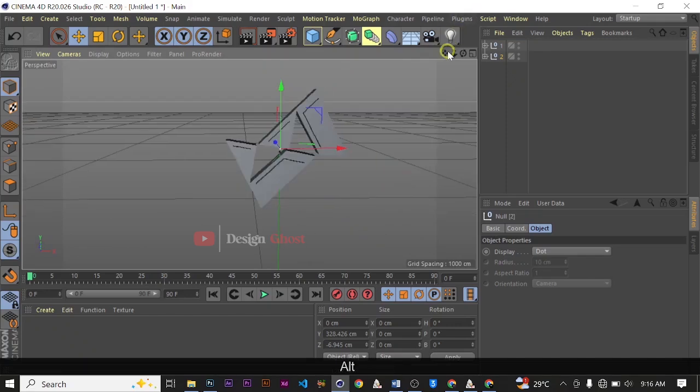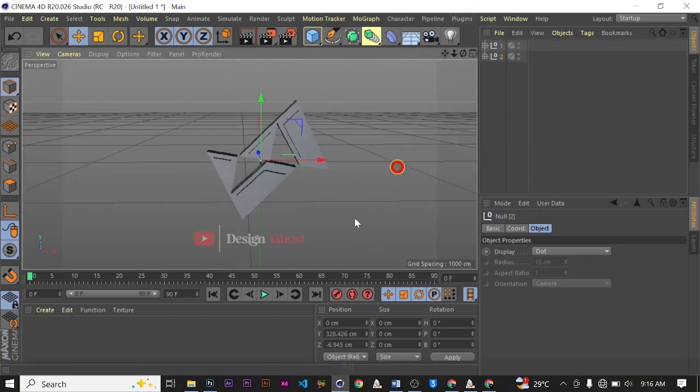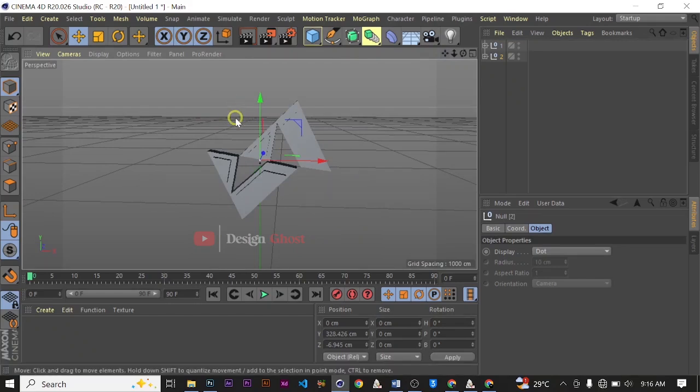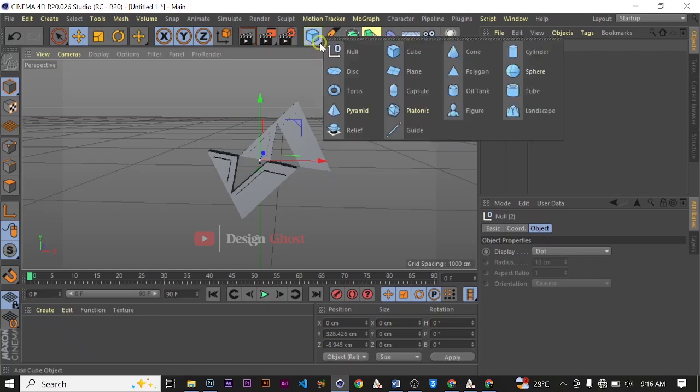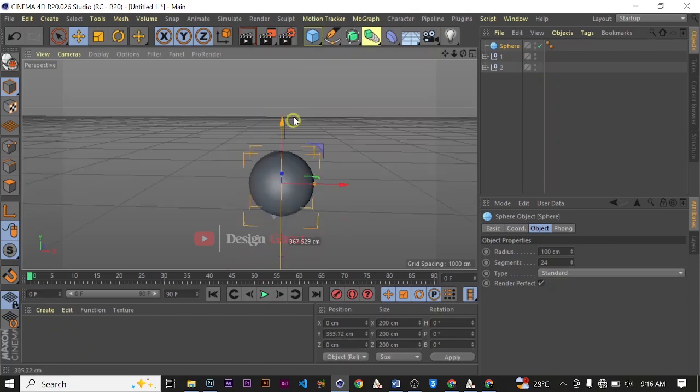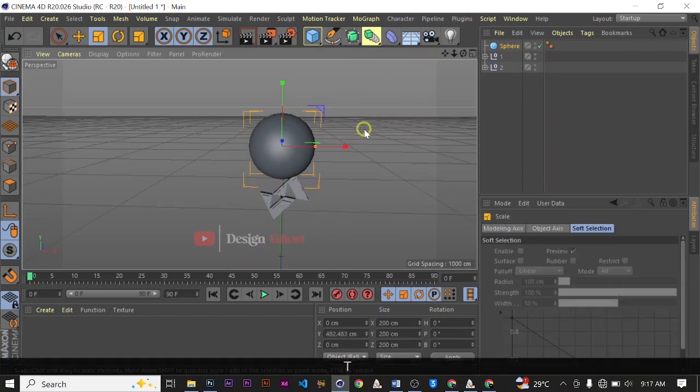And back in Photoshop, we realized that our logo had a round object here. Because we were going to use a simple sphere in Cinema 4D, that is why we did not make a work path of it to bring it here. Okay, so we are going to add our sphere, bring it up, and make it small.